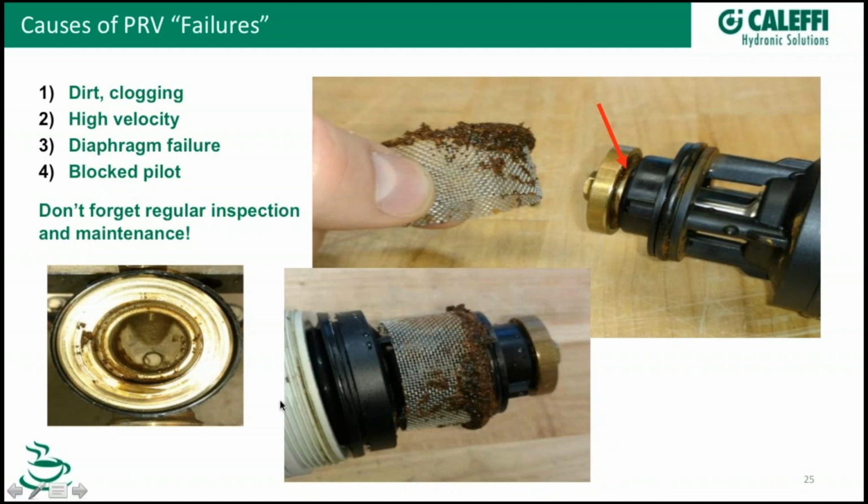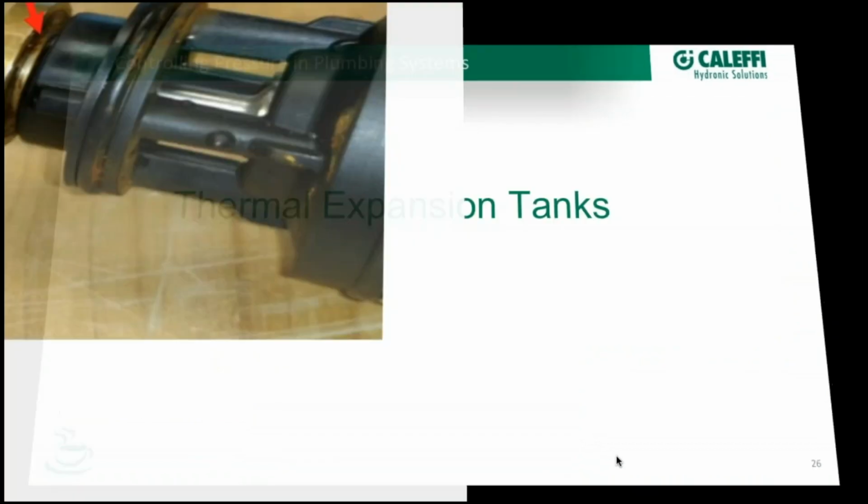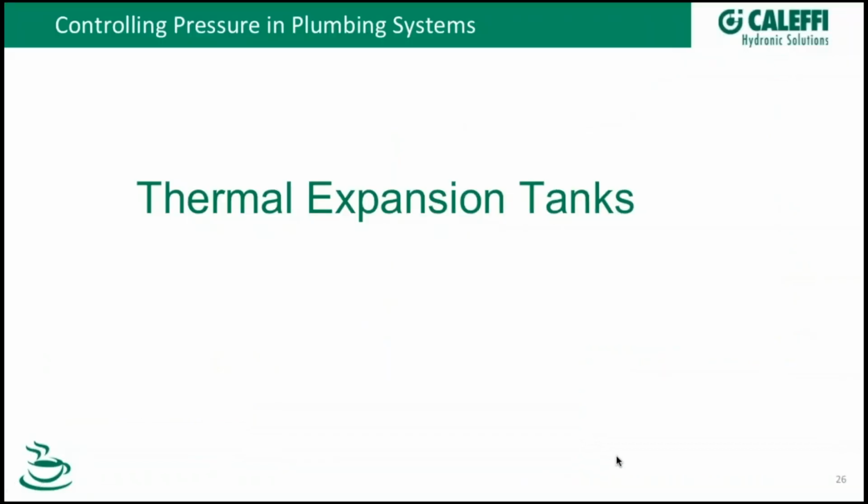So the beauty of this valve also is, right there is how you take this cartridge out, and you can almost do it by hand. It takes a channel lock typically because you've got an O-ring seal up here, but you don't have to take like 18 bolts out of the top of this regulator to get it apart and service it to clean it out. Or if you have to change a cartridge because something got damaged in here from a sharp rock or something, you just unscrew it right here from the body and this whole cartridge can be replaced. So it's a really simple valve to clean, maintain, or take apart and check if you've got something going on in there that shouldn't be.